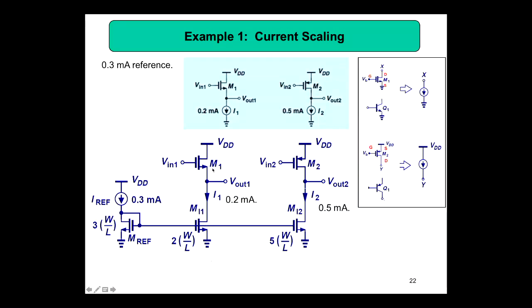When you have a current mirror, you have to design it, and you should know how to connect it to the amplifier of interest, because that is very important. You should calculate how much current is required here. Based on that, you design your current mirror, and decide whether you need NMOS or PMOS. Because this is a current source from the point to the ground, we have selected NMOS.